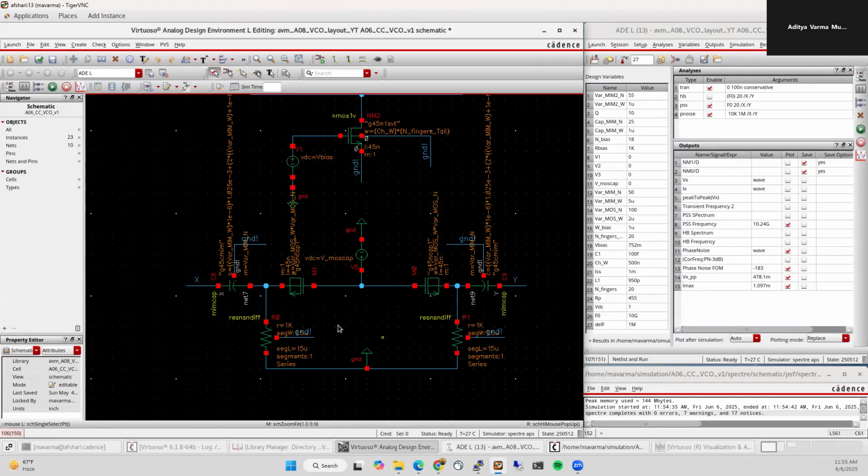The second major one is that we need to flip these varactors. The reason we need to flip them is that when we do the layouts, the body contact of this MOSFET, this MOS cap, I guess, needs to be grounded. And that's because the body is shared between all transistors on the chip, at least in this process. So in some processes, you have like an isolated body, and in that case, you can have a separate voltage for the body. But for these MOS caps, at least the body is shared.